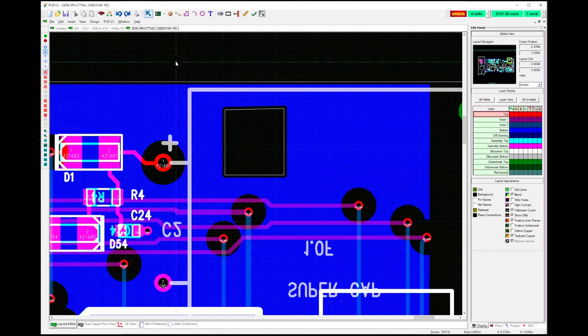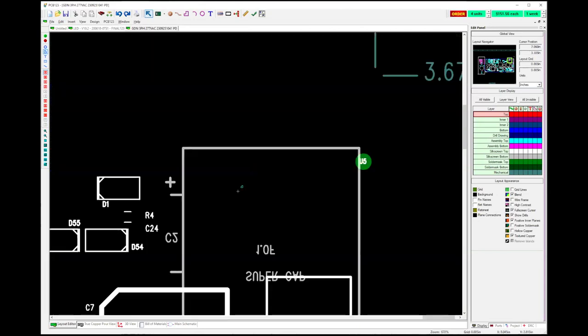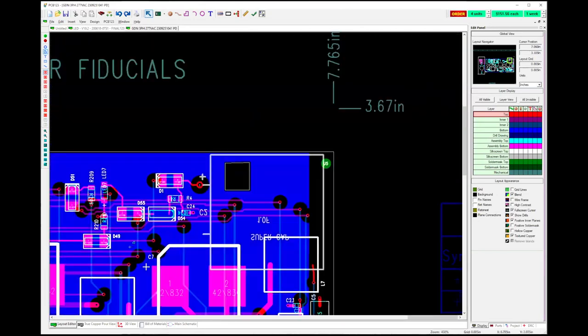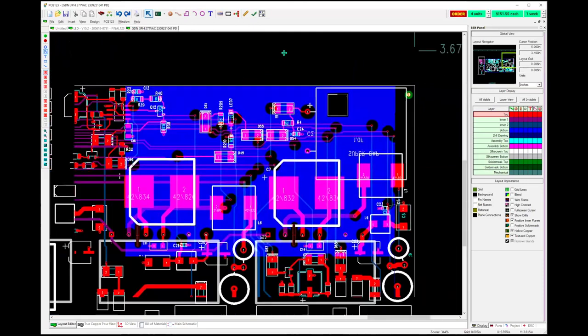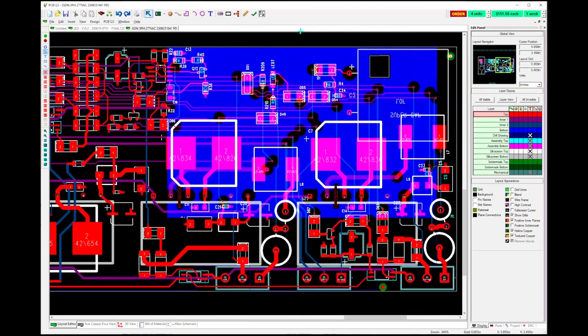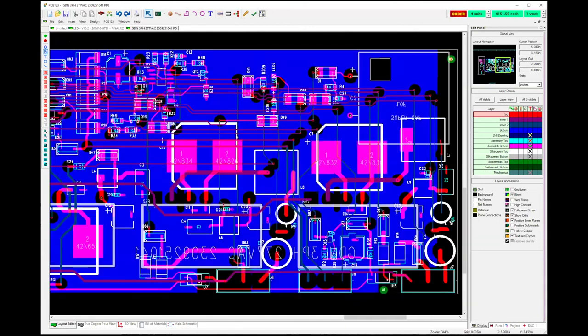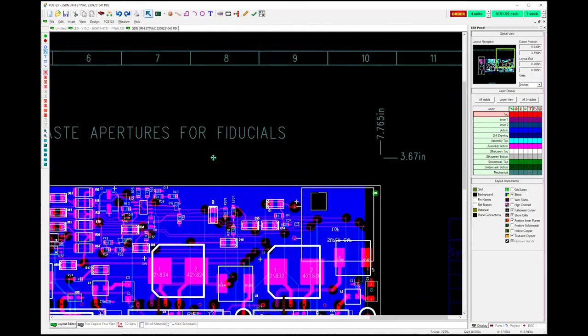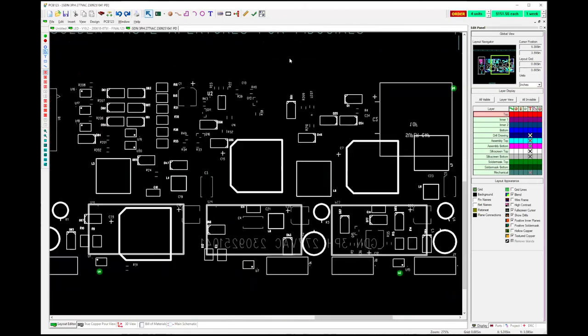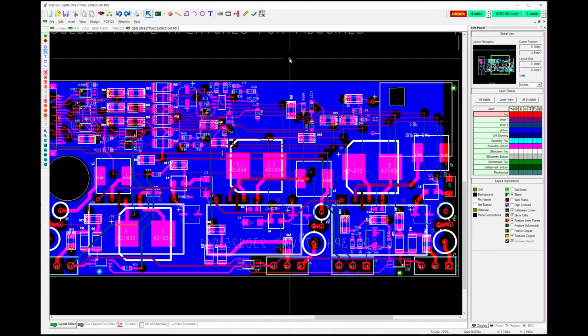It was more involved than that. I had to import the graphics into a Gerber editor and then save that Gerber and then import that into my board file to get the actual image I wanted. It was a pretty involved process. I got pretty good at it when I was working at Sunstone years ago, but if you don't have an actual Gerber editing tool, you probably won't be able to pull it off. Did that answer the question at all?